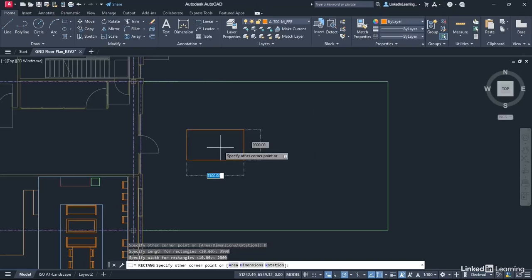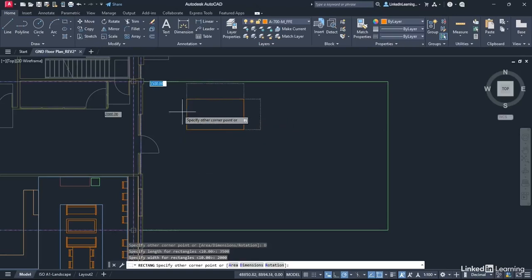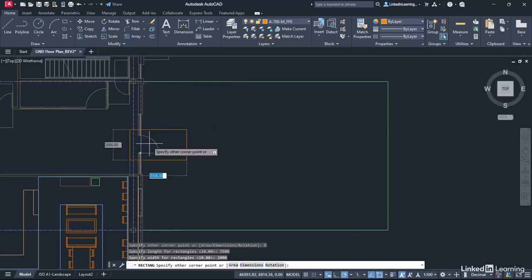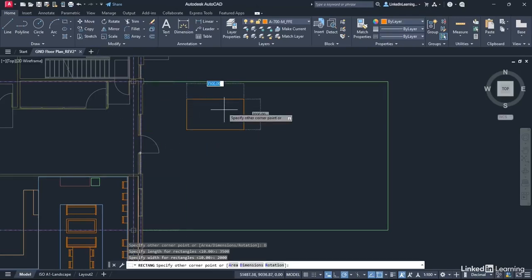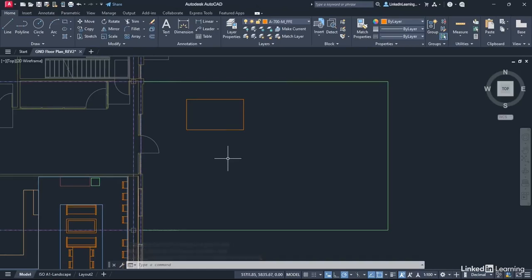Press enter. So there's your rectangle, but as you rotate now, can you see you can now rotate it around that original point that you clicked, which is great for orientation in a drawing if you need to specify it. So we're going to place it here, sort of top right. If you look as you go round, top right, just left click once, job done. There's our rectangular outdoor table, 3,500 by 2,000 millimeters. Very quick and easy.